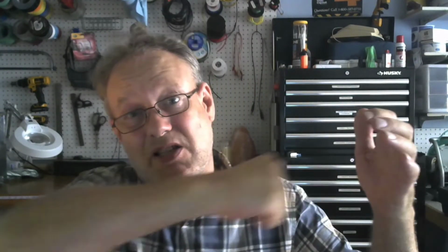So you guys already know about cushioning and why we would use cushioning. That's important as well. If it's going to extend really quickly and hit the end really quickly, you want cushioning on the outside. But if it's going to retract slowly and it's not even going to retract all the way, you don't need cushioning on the rear. If you don't know what cushioning is, go to the actuator week, I forget, week 3, when we talked about actuators.